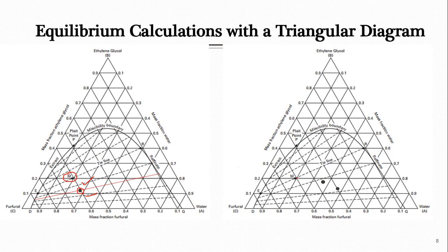In this diagram you see this is the original M point, and now I have shown two more points for M. One point is this and the other point is this. So let's look at the tie line for these. From the discussion which we have done so far, overall this point M is now located more close to the upper tie line in this region. So the tie line passing through this M point and joining raffinate and extract composition will have behavior more close towards this tie line as compared to the down one.